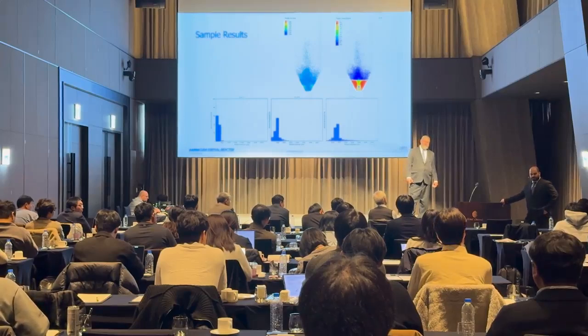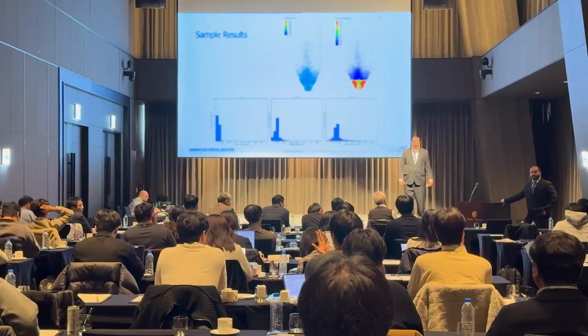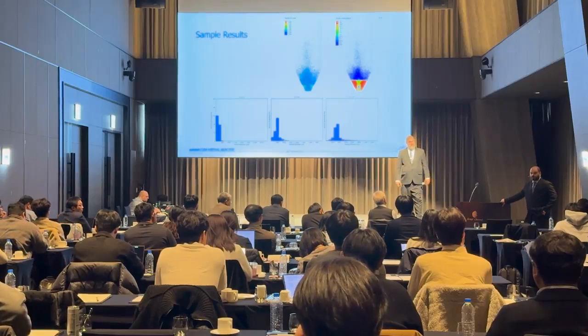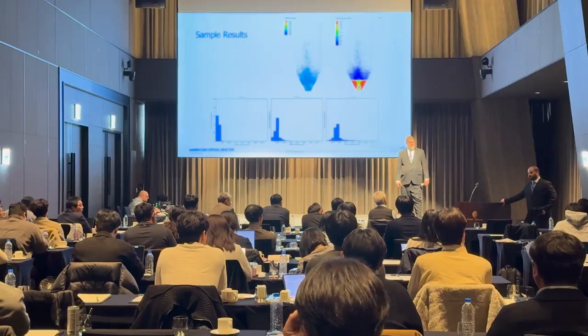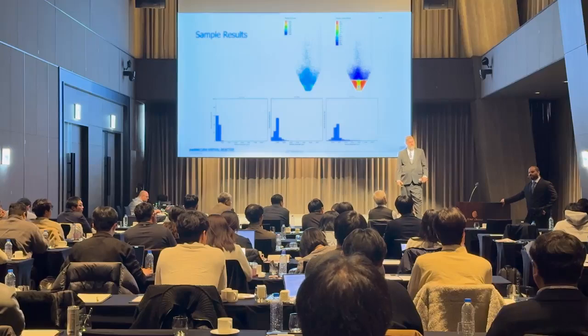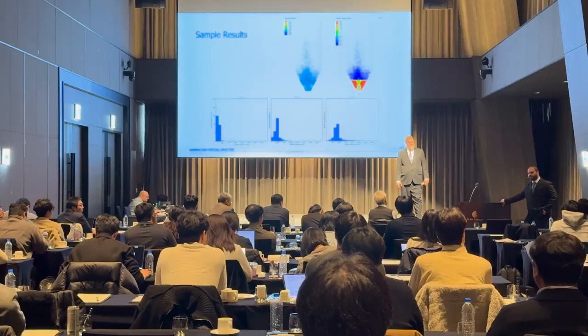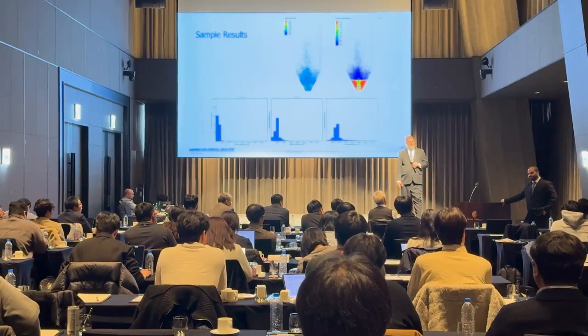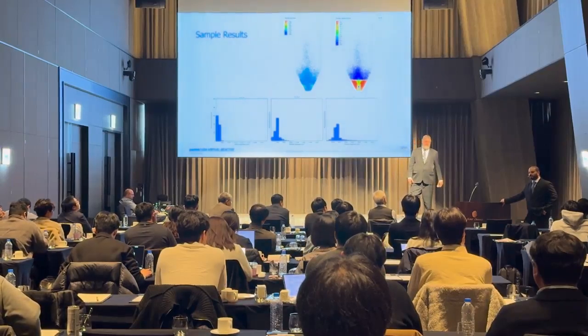But I think that is something that has come up a few times where we do want to have, as you call it, local close pack volume fractions, depending on if there's a local PSD that's different, that can change. Yes, that is something under consideration for development here. But as of now, if it is the same species, it will have a constant, what I call a single close pack volume fraction. Different species, though, can have different close pack volume fractions.